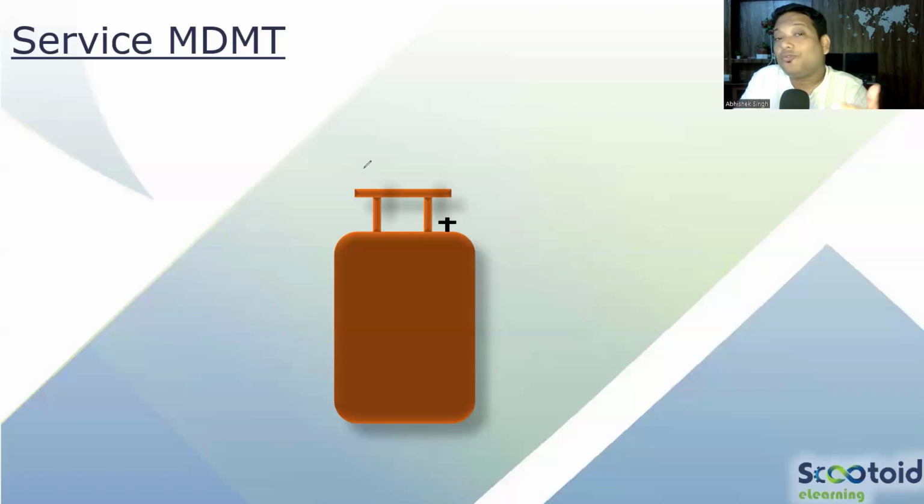Now, how do we find the temperature achieved because of that? That is done by the client, meaning the process department. When the P&ID is finalized and they are ready for HAZOP, the study called the depressurization study is done. In that, they locate the valves which may open up and allow the liquid to flow and depressurize. So what will be the effect of that on your pressure vessel? That study is done, and based on that you get the service MDMT.